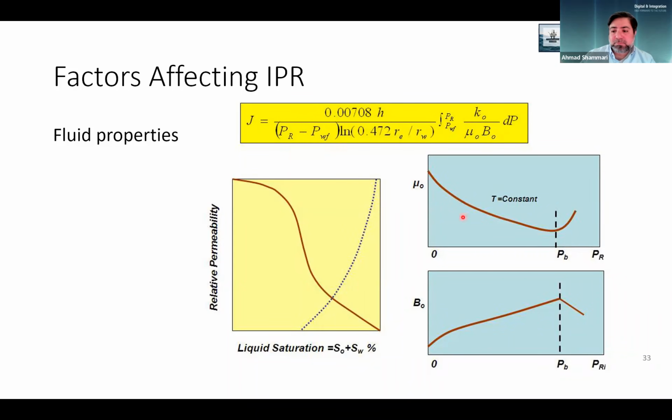Similarly, the viscosity. Now the viscosity also changes with temperature. So for areas where we have heavy oil, meaning of course high density, this will also affect the viscosity. How can we reduce the viscosity and make the oil more mobile? Well, by heating it. And that's why we inject steam. So we inject steam to heat the reservoir up, and this will reduce the viscosity of oil, and this will allow oil to move easily to the completion.